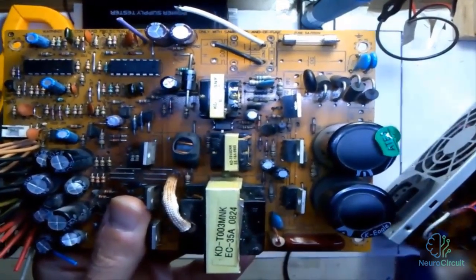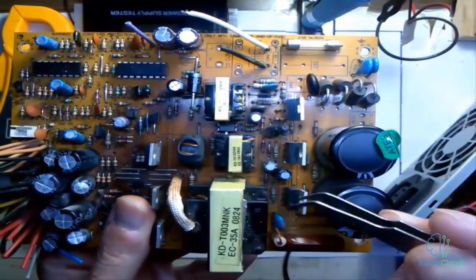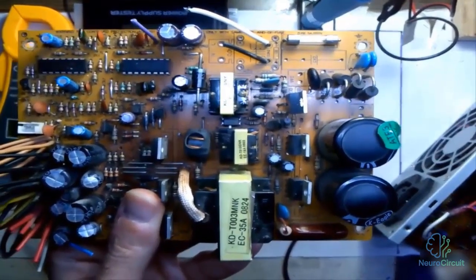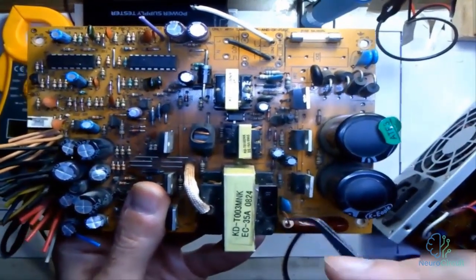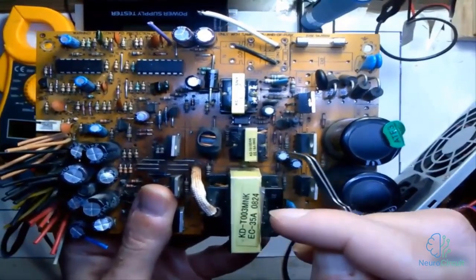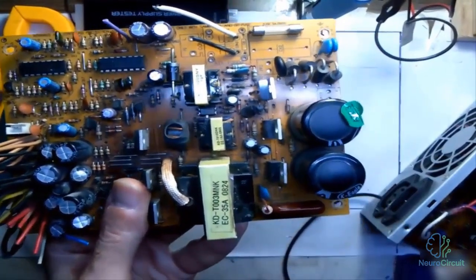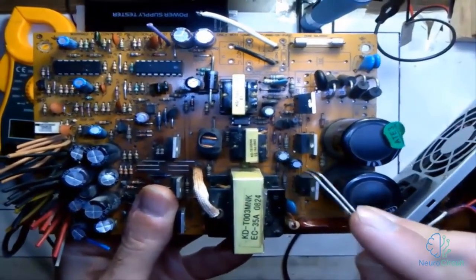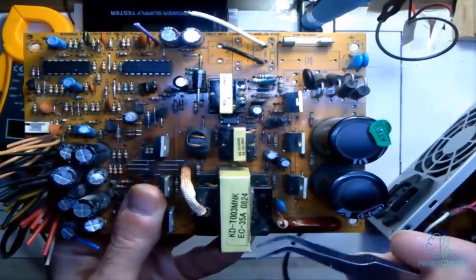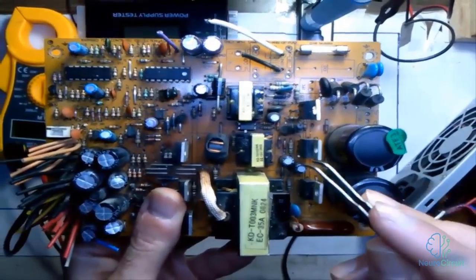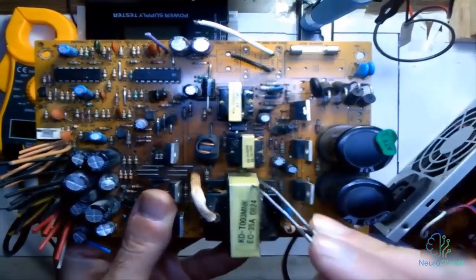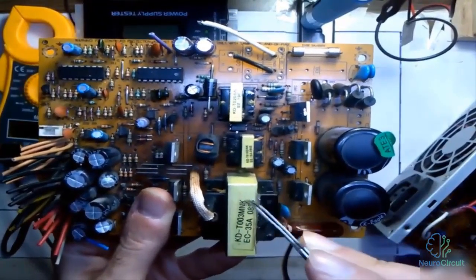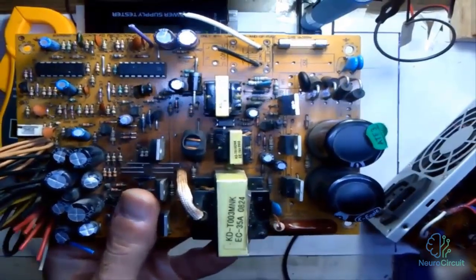In other words, we will actually have the same 300 volts AC, but with frequencies that are adjustable. This is the fundamental principle behind the operation of switching power supplies. Based on the circuit that has been designed here, which will be explained more and more in the next sessions, there are circuits placed here that, with the help of the transistor, generate various pulses and frequencies. These frequencies or sinusoidal waves that enter the transformer pass through the transformer, and the transformer, by reducing the voltage, generates the output voltages for us.